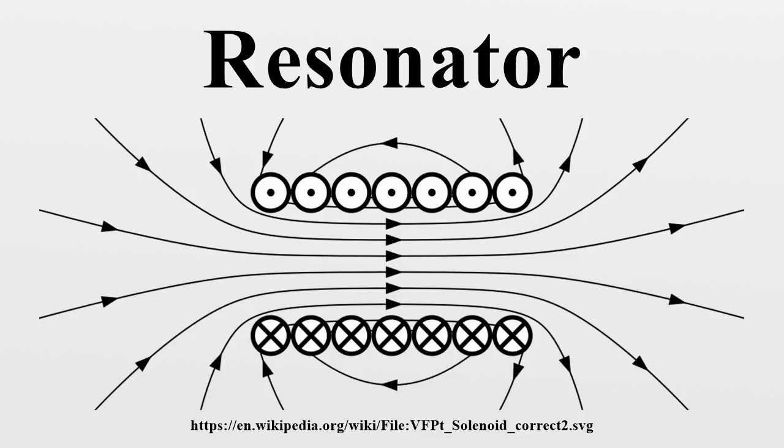Mechanical resonators are used in electronic circuits to generate signals of a precise frequency. For example, piezoelectric resonators, commonly made from quartz, are used as frequency references. Common designs consist of electrodes attached to a piece of quartz, in the shape of a rectangular plate for high-frequency applications, or in the shape of a tuning fork for low-frequency applications. The high dimensional stability and low temperature coefficient of quartz helps keep the resonant frequency constant.